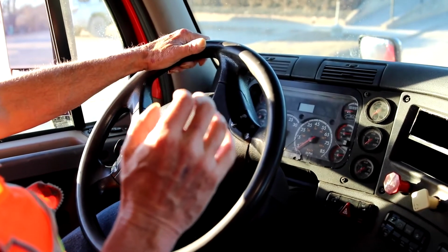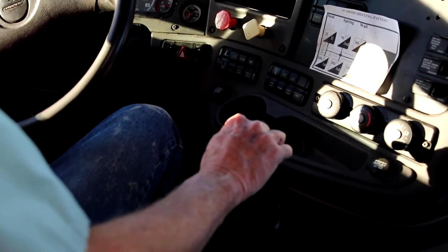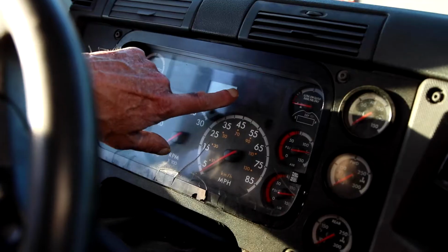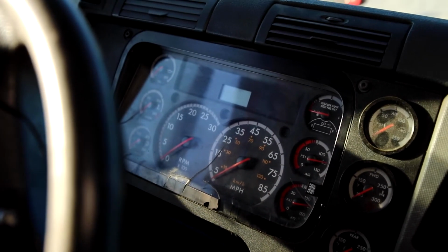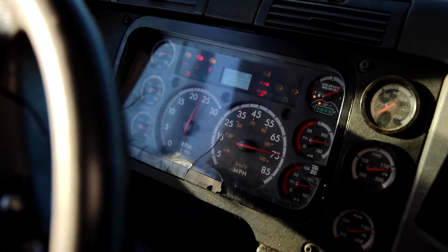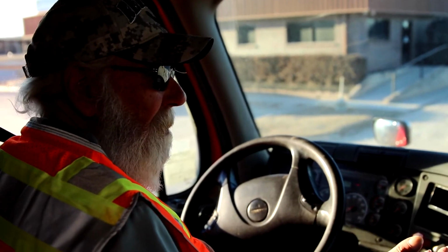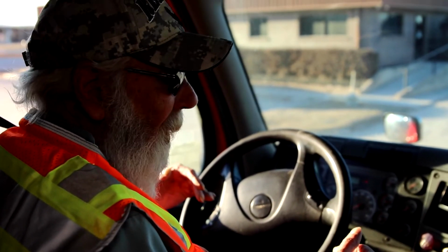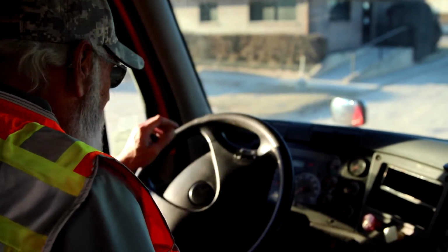To conduct the safe start, you want to press your clutch all the way to the floor, ensure the vehicle is in neutral. Turn the key on, get all your warning lights up. You're looking for your ABS warning light, which came on and went off in a very big hurry. Release your clutch. Don't jump away from it just in case the truck is in gear.